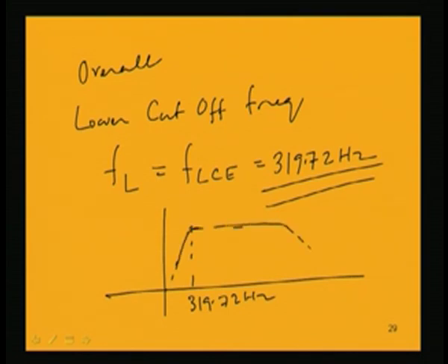This type of voltage gain we actually get in the amplifier because of all those capacitances. So, this is the value of the lower cutoff frequency FL, because at this point the voltage gain drops to 1 by root 2 times AV, if this is AV. So, out of all these three we have selected this value.